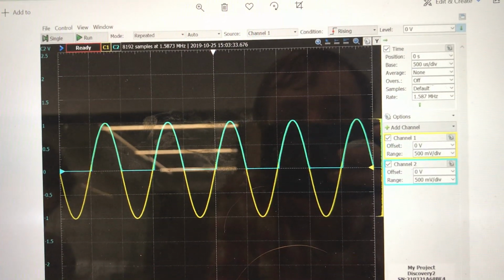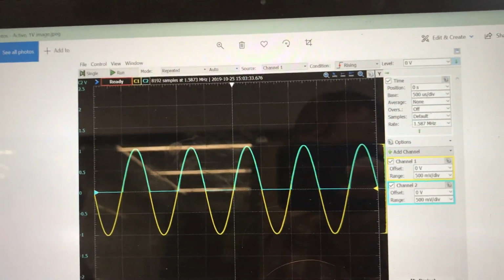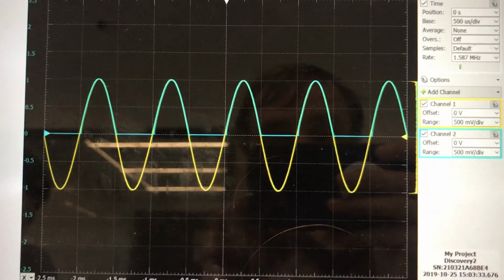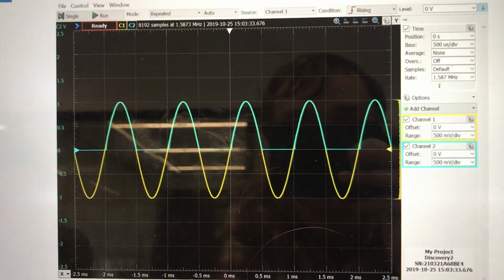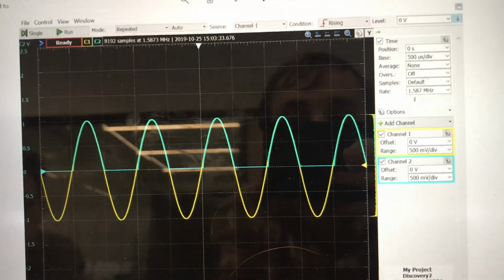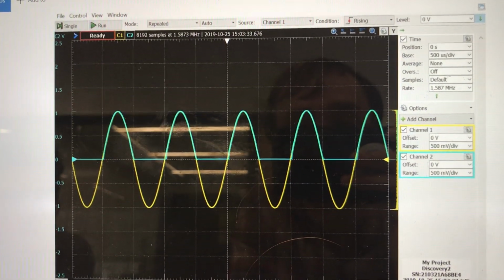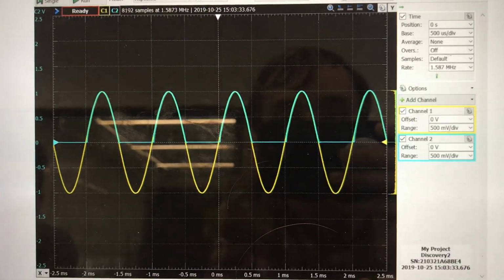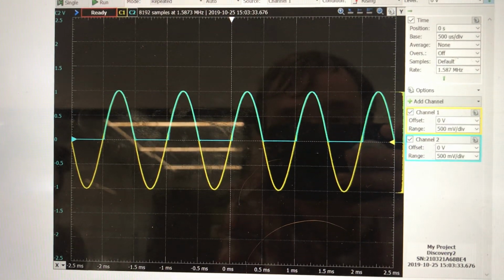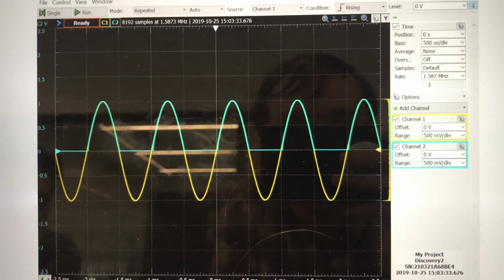Now this is the active half-wave rectifier. Now we see the voltages match exactly because we have power to do it actively. So it rectifies the half-wave without any voltage drop. That's at 1 volt amplitude, so 2 volt peak to peak, and it's perfect.